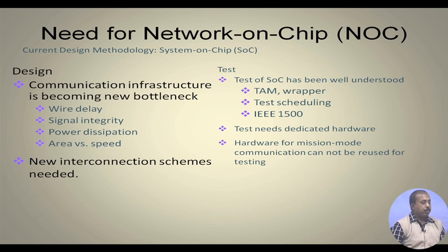So, for testing purpose, this is for the design side. For the testing side, test of SOC is well understood. We have seen how it can be done, like the TAM design, the wrapper design, then the test scheduling problem, and the IEEE 1500 standard. That has told the standard interface of these core wrappers.